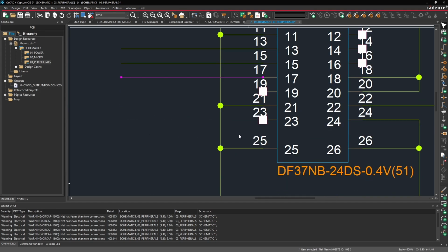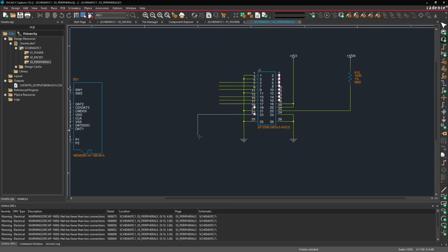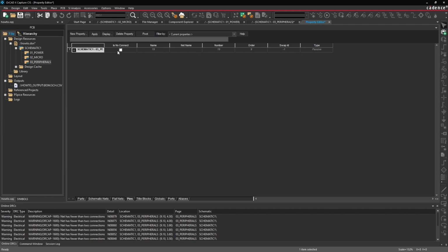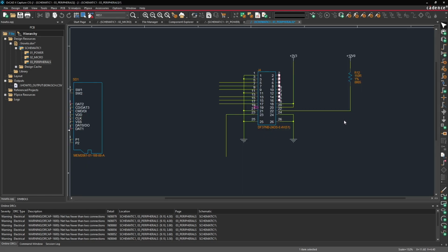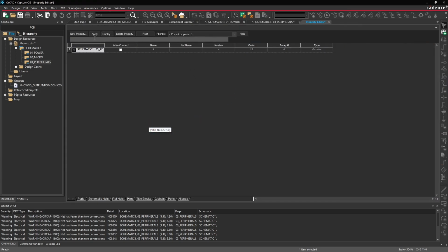And actually pin 23, we'll connect that in a second. This is the cathode side of basically this giant LCD backlight. So we're going to connect that through a transistor in a second. Pin 19, let's go set that as a no connect. And then on this side, we have everything except for pin 4, I believe.